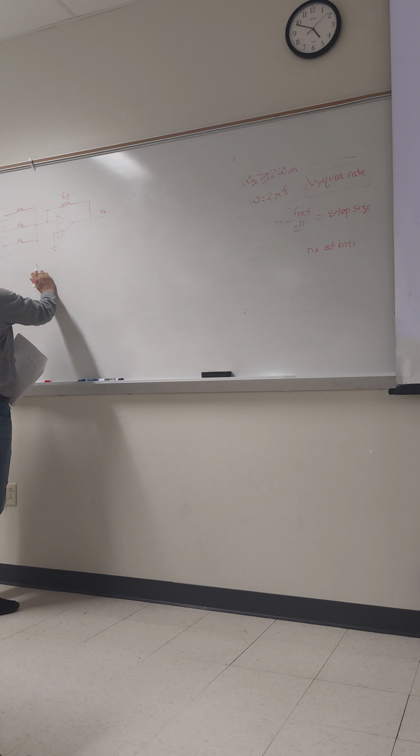Okay. So dithering is the important one. What is dithering? It adds a small amount of controlled noise. This is a noise actually, not your signal. If there is anything other than signal, we consider it noise. For example, we round at, say, 3.5, and we just add 0.2.